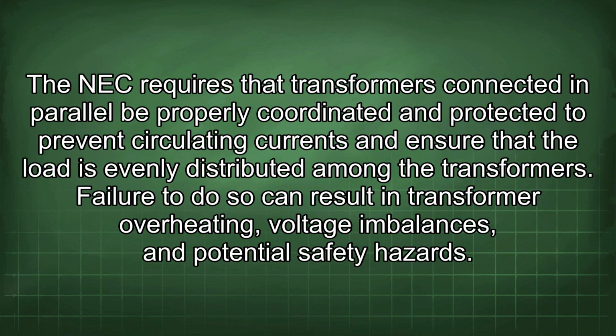The NEC requires that transformers connected in parallel be properly coordinated and protected to prevent circulating currents and ensure that the load is evenly distributed among the transformers. Failure to do so can result in transformer overheating, voltage imbalances, and potential safety hazards.